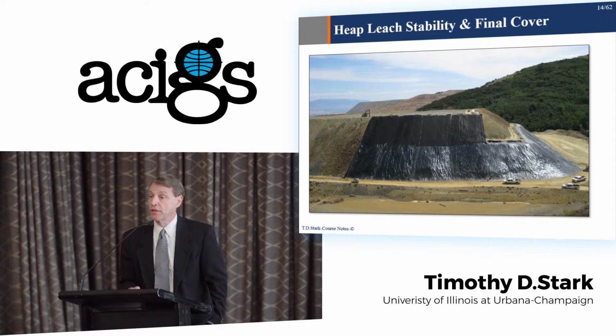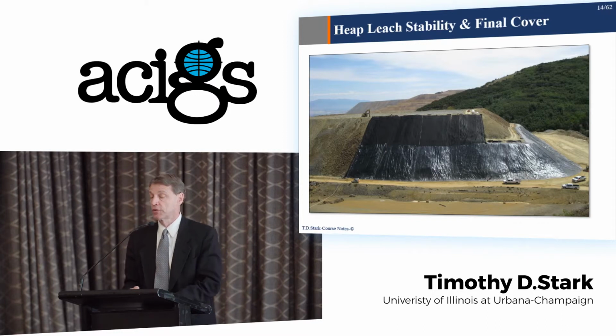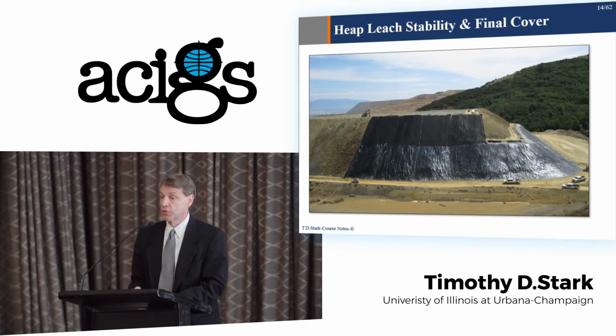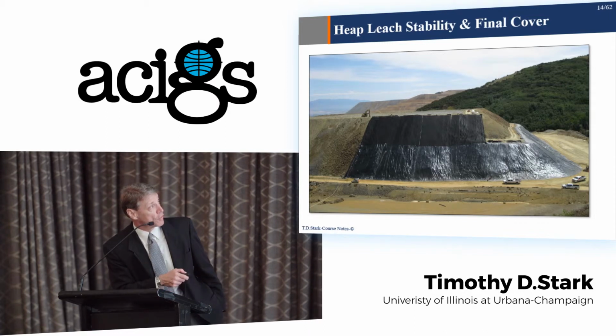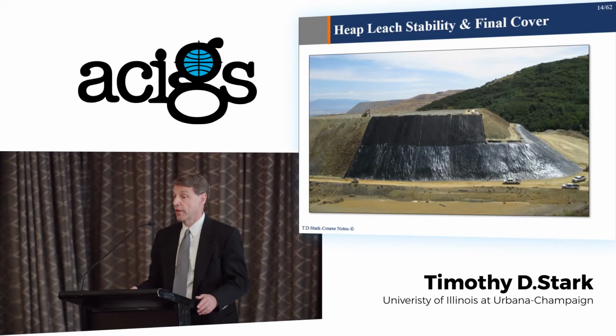A number of cases will want a cover system over top of the heap leach for a variety of reasons. One, it could be to control the temperature of the process occurring in the heap leach pad, or it could be to reduce infiltration. But here's one where the cover's coming up, and you can see a pretty steep slope for that cover.